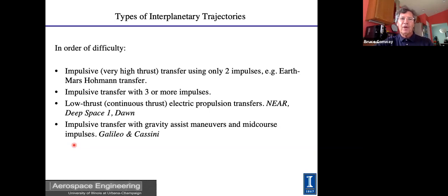But when you're in field-free space, remember that delta V equals A, acceleration, times delta T. So even though the acceleration is very small, down to maybe 10 to the minus 5 G, the burn time, compared to the space shuttle, instead of maybe 10 to the 2nd seconds, goes to 10 to the 5th or 10 to the 6th. So the product of acceleration times time gets you to roughly the same final velocity as the larger thrust engine.